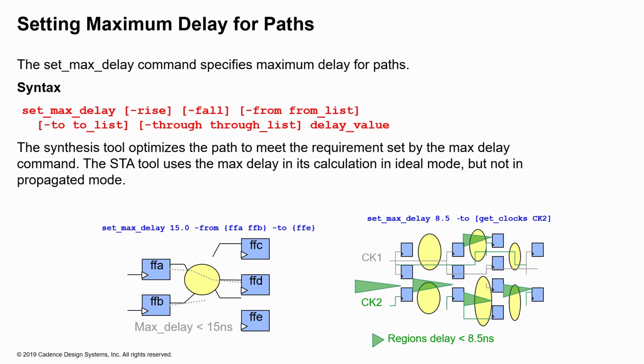In ideal mode, you can use the set max delay command to optimize the delays along a path and meet the requirements set by the max delay command. And the synthesis tools can actually benefit from this command being set.